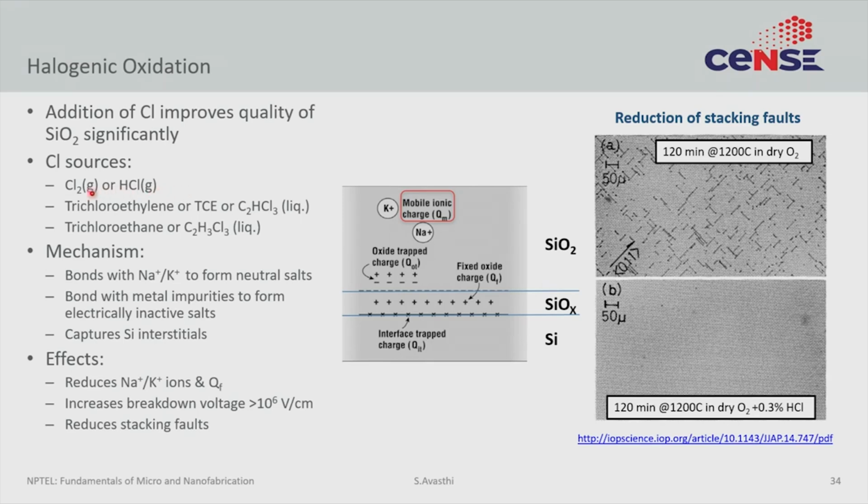The other thing to care about is that both of these gases are very corrosive. So even if you have a very high quality stainless steel tubing or stainless steel housing, etc., small amounts of leaks would cause a lot of corrosion in those steel lines.